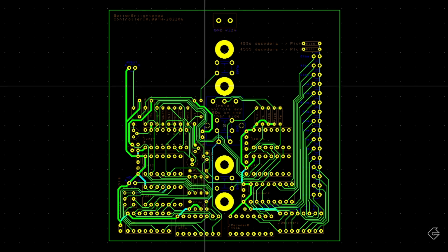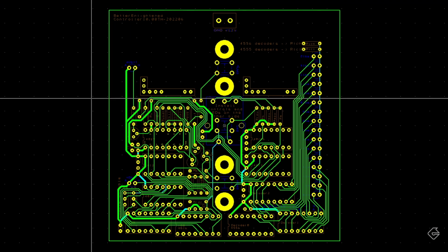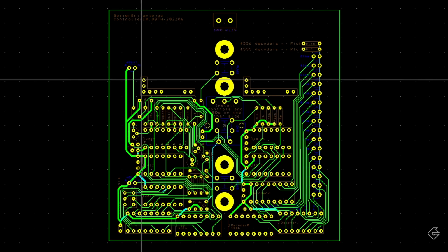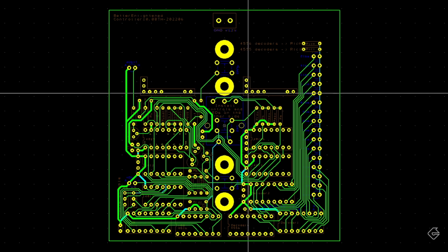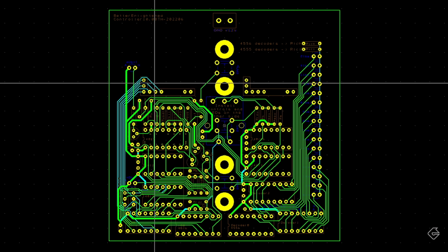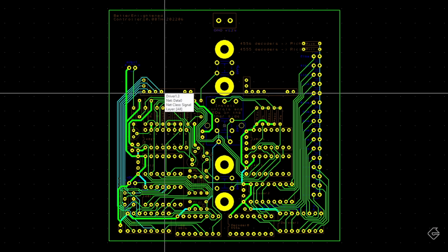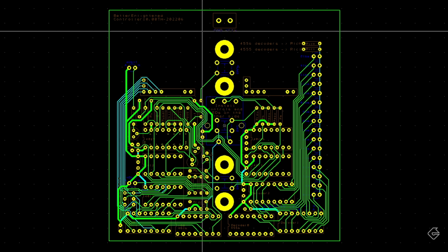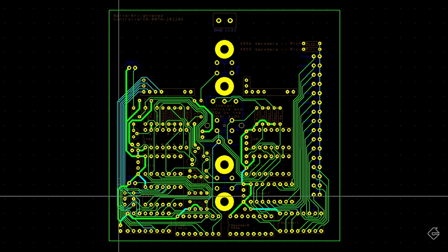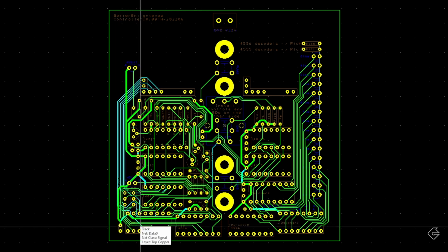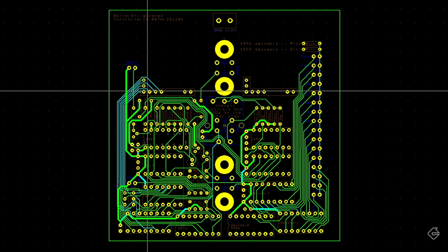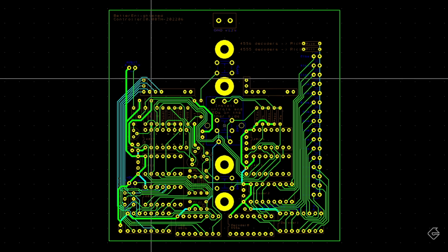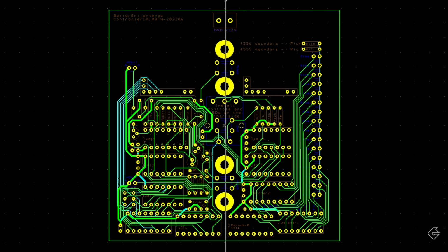And in this clear zone, I'm going to put in the footprint for our LED driver connectors. These connectors should look familiar. You saw them earlier on the driver, and you can clearly see that there's two, one over here and one over here. Let's wire them up. The first traces I've added are the data lines. So these are the data lines from 0 all the way to 5, so the six data lines. I put them all on the second layer of this board. Now, because we have two drivers, I want to make sure that the data lines that show up on this driver also show up on this driver.